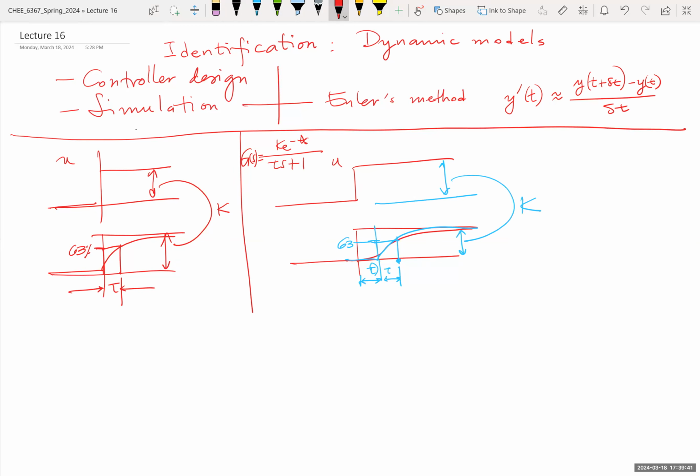And even if you have second order systems, if they are overdamped, you approximate them like this. If they are underdamped, and for this kind of change, you may get something like this. There are ways to get the overshoot, this over that, or the damping factor.